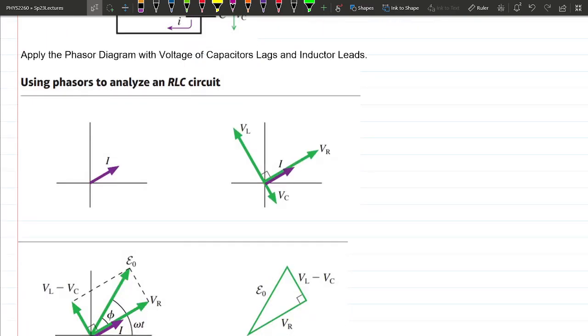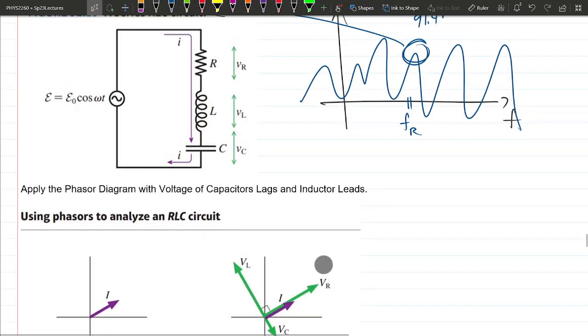So you're going to do the same steps as what we did with the RC circuit, right? We're going to do a phasor diagram where there are no units on these axes, right? What we're going to do is put the current in one direction. So that's our reference. The reason we're picking current is that all of this stuff is in series with each other, right? There's only one current, right? So we're going to use that as a reference, okay?